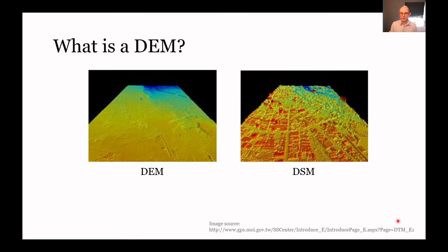So just to quickly illustrate the difference between the DEM and the DSM, this is the same area. We can see here that all the buildings that are visible in this digital surface model have been removed from here, and we just interpolate straight over from the sides of the buildings so that we have the ground surface. Now, of course, there could be errors with this. We have no idea what's happening below ground. There could be basements here, things like this. So there are always limitations, especially in these built environments. But this is generally what we're looking at.